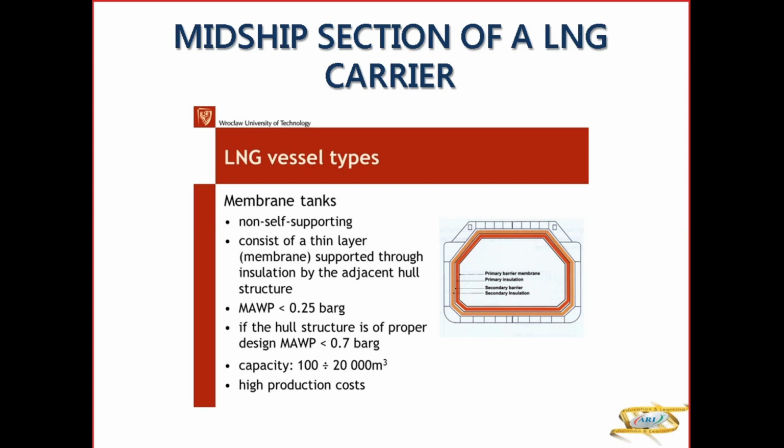Now, this is your LNG type vessel. So these are your membrane tanks. These are non-self-supporting. They are basically part of the hull. They consist of a thin layer membrane supported through insulation by the adjacent hull structure. The hull structure gives the capacity.